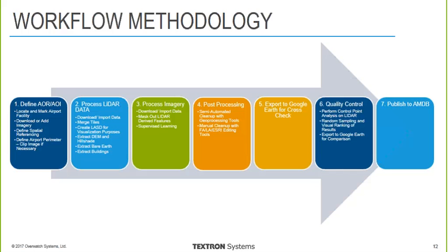Once we've essentially extracted all of our GIS elements, we're ready to do post-processing, and that consists of automated and manual cleanup steps. This is where we're going to start to finalize our data. Semi-automated means we could square up buildings, we can use aggregation to clean up noise, we can do smoothing to give our results more of either a hand-drawn appearance, or if we have line work, we can give it a rigid type of smoothing to make roads more linear and so forth.